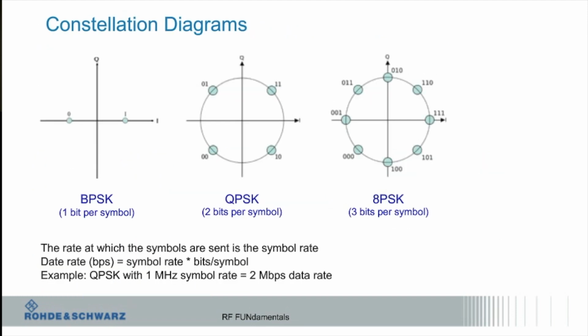Okay. So if I look at the different constellations, BPSK, there's 2 points, right? Binary, like that. QPSK, quadrature, so that means there's 4, right? Quad is 4. There's 8PSK, and there were a few things around that did that. You don't really see this all that often. You really see variants of this, including an amplitude level, and you'll see that in just a minute.